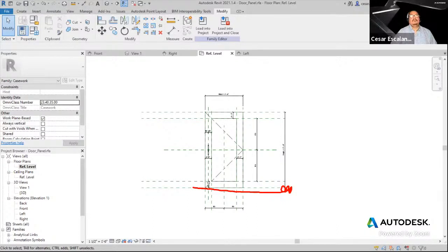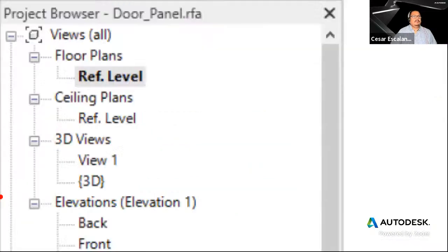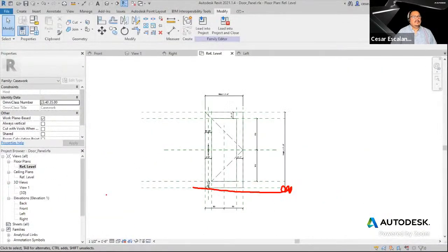And nothing wrong with this. You could have built it horizontally, but in elevation, you need to create additional reference planes, and because the template already comes with a width and a height, and is already prepared, the box is prepared for you, I thought it was better to use the plan view than the elevation. But technically you can do it also in elevation. It's just going to be additional reference planes that you need to build in an elevation view.